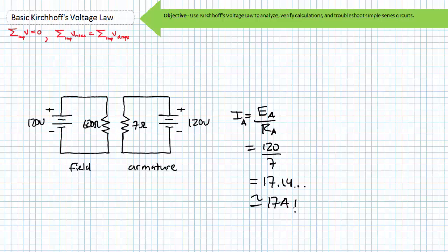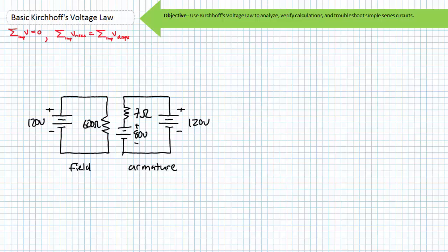Again, you need not worry about the nitty-gritty details of this phenomenon if you can understand this model. Counter-electromotive force is represented as a series opposing voltage source. Let's say at rated speed, this motor produces 80 volts of CEMF. This 80 volts of CEMF pushes back on the armature supply voltage.